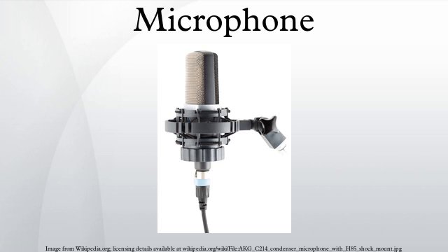Though electret microphones were once considered low quality, the best ones can now rival traditional condenser microphones in every respect and can even offer the long-term stability and ultra-flat response needed for a measurement microphone. Unlike other capacitor microphones, they require no polarizing voltage, but often contain an integrated preamplifier that does require power.